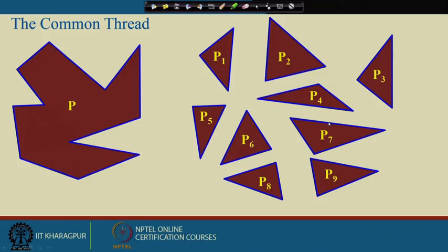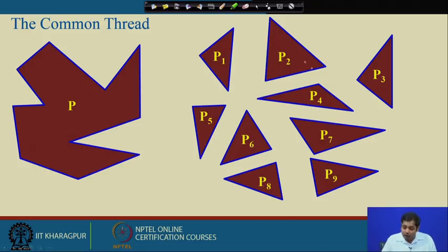We divide the entire problem into small sub problems such that for each sub problem we know the equations. We know how to represent those sub problems through a mathematical model. We know how to represent each resistor, V is equal to IR. We know the relation between stiffness and the displacement of individual springs. So we can write equations for each sub problem, and then once we write the equation for each sub problem, in the case of the electrical resistor problem, we wrote V is equal to V1 plus V2 plus V3. In the case of the spring problem, it was x is equal to x1 plus x2 plus x3.